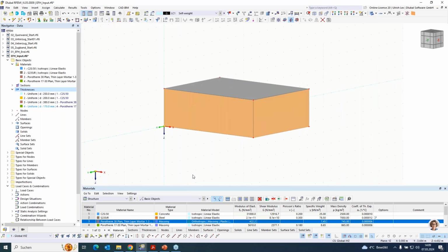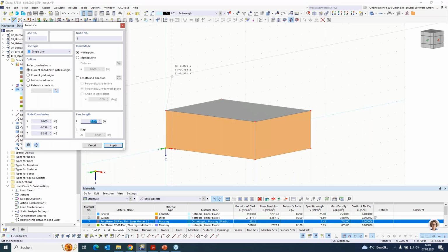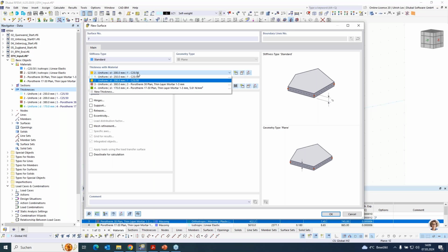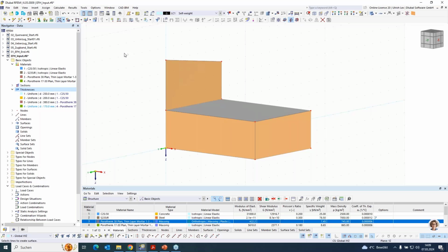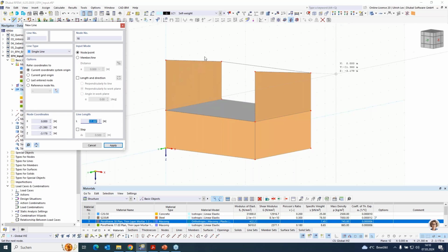So the second floor will be in the front a height of 4 meters and in the back a height of 3 meters. And as I did it before, I can use select boundary with 380 millimeters and can select and copy this surface. And at the end, the wall in the front and at the back.